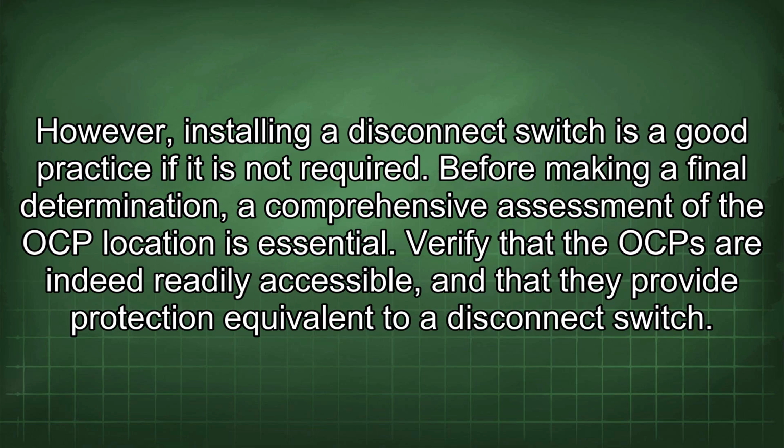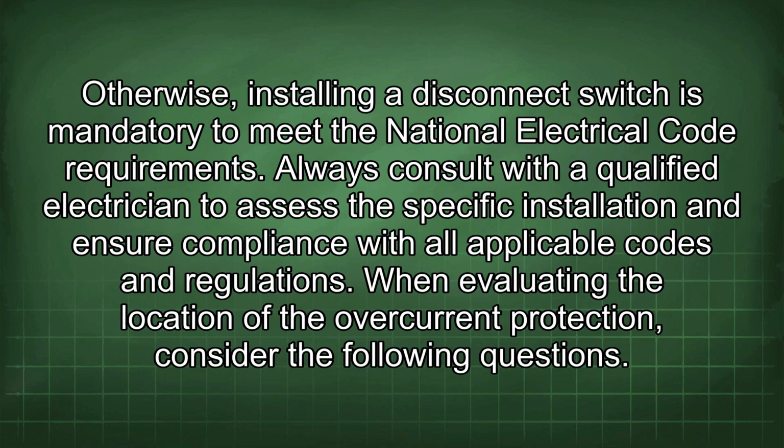Before making a final determination, a comprehensive assessment of the OCP location is essential. Verify that the OCP are indeed readily accessible and that they provide protection equivalent to a disconnect switch. Otherwise, installing a disconnect switch is mandatory to meet the National Electrical Code requirements. Always consult with a qualified electrician to assess the specific installation and ensure compliance with all applicable codes and regulations.